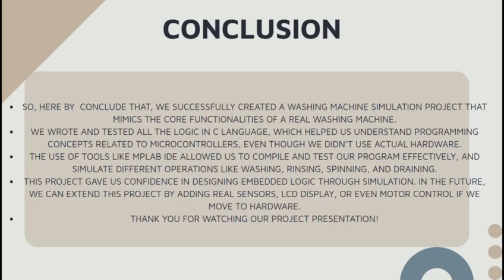We used MPLAB IDE as our development tool, which helped us write, compile, and simulate the behavior of our program effectively. The entire logic was written in C language, which not only improved our programming skills but also gave us practical exposure to embedded systems concepts such as timers, state machines, and input output control.